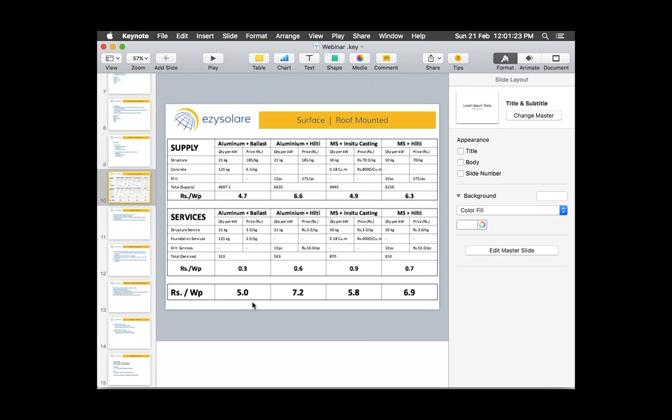So whatever sections will come, how you anchor them, how you ballast them, that will be captured in the detailed design, and your design consultant should be able to capture that, which I'm sure any good design guy would do. But from the material perspective, you go with anti-corrosive ones. There are even paints coming in the market. Even after galvanization, they prefer putting on paints of zinc primer. So you can even explore that option.